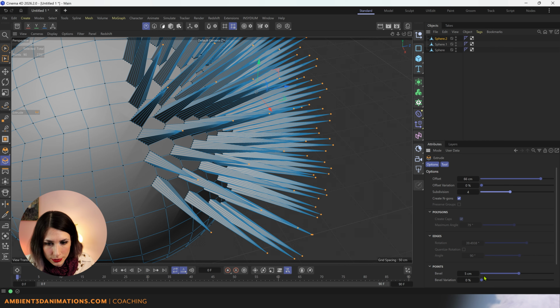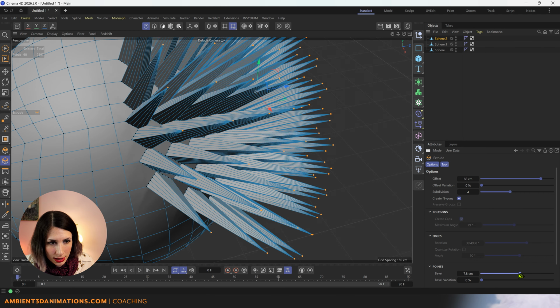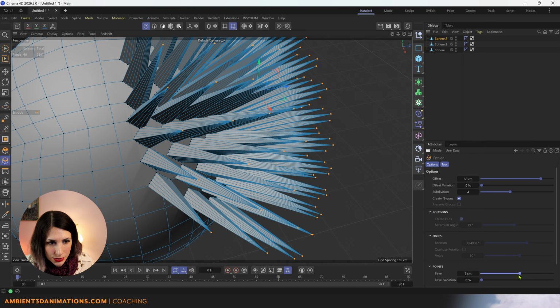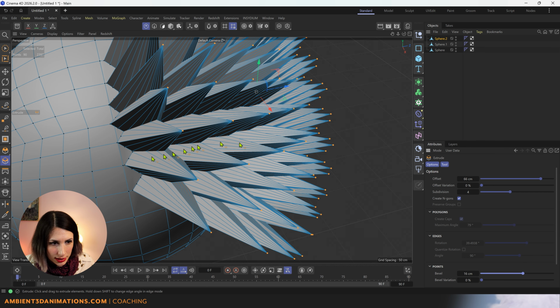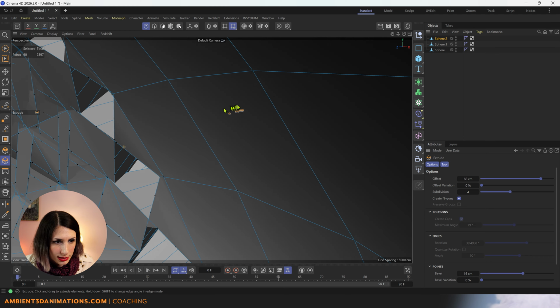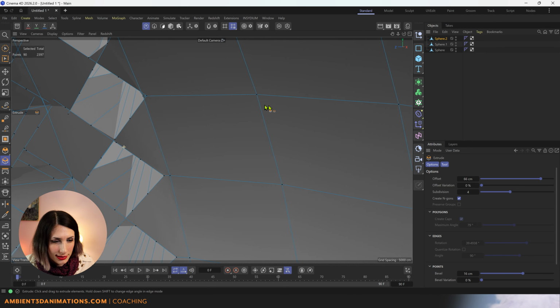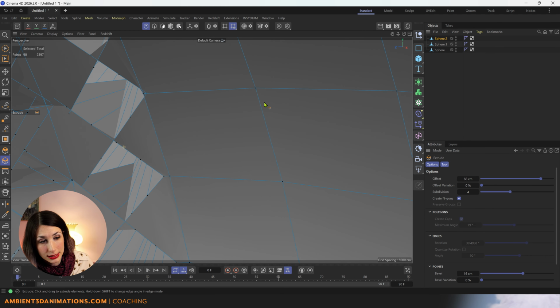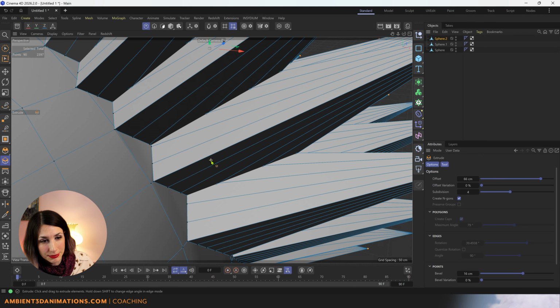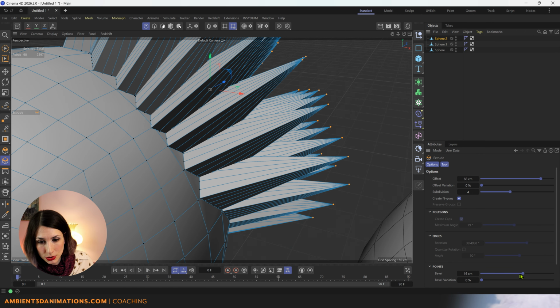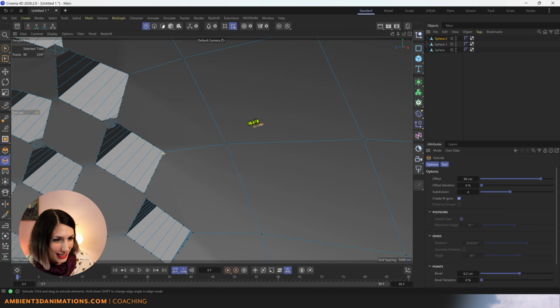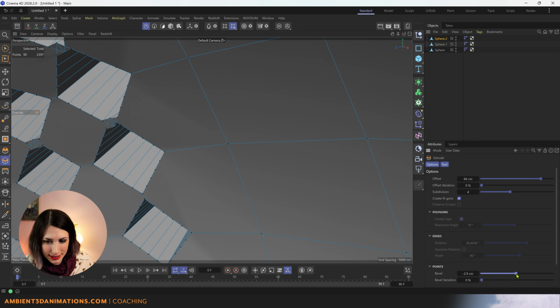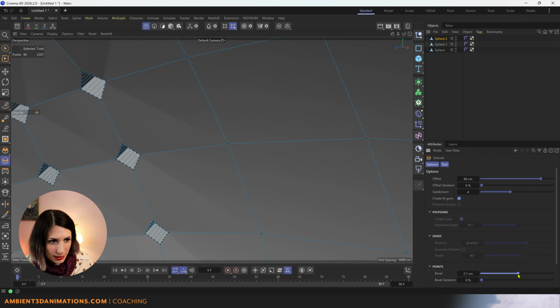You can control your bevel here, and that's basically controlling the base of your point extrusion. You really don't want these to intersect though, so just keep that in mind, because that becomes real messy. Like, you can't 3D print that. Let me just say that. That's not gonna make sense to your 3D printer. So be careful with adjusting the bevel. Make sure that those aren't intersecting, because you'll really confuse things, confuse your computer. Be careful there.